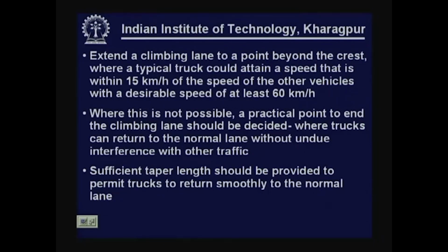Why is this said? Because on long grades where you are providing the climbing lane, it is expected that the speed deviation will be substantial. So, once it has reached the crest, the immediate speed gain may not be sufficient to limit the speed deviation within 15 km per hour.